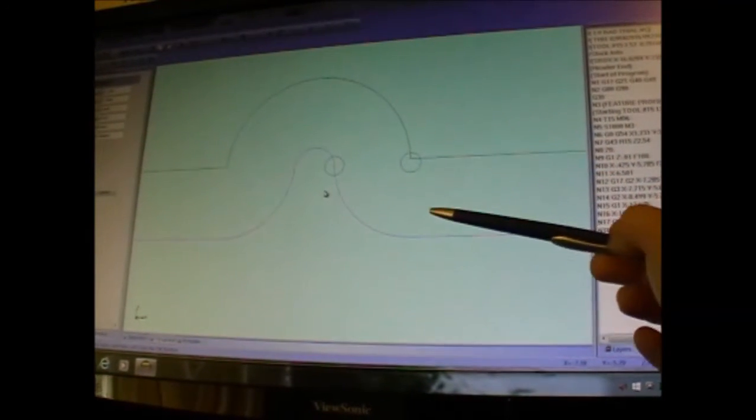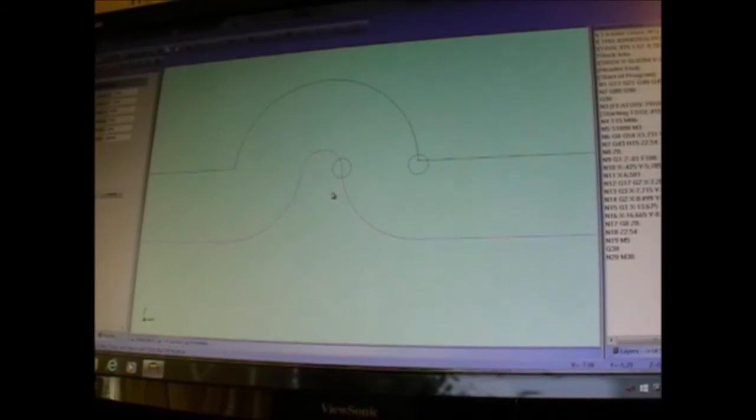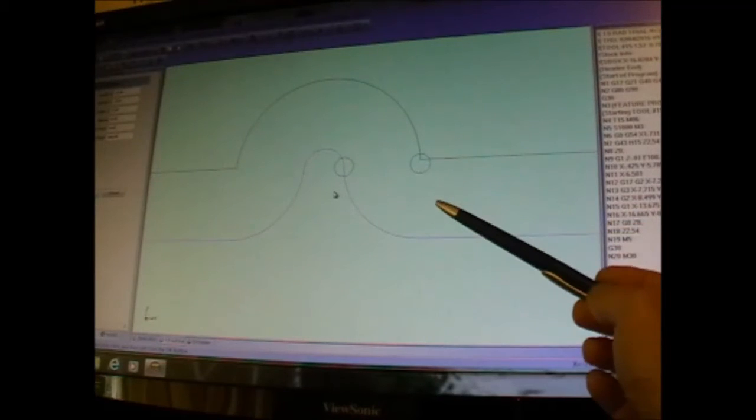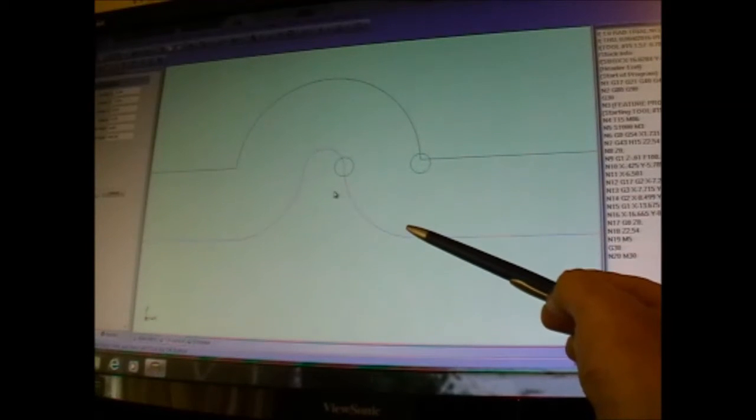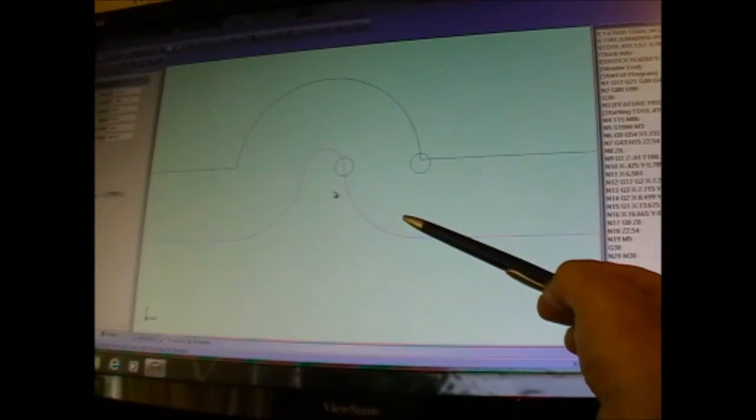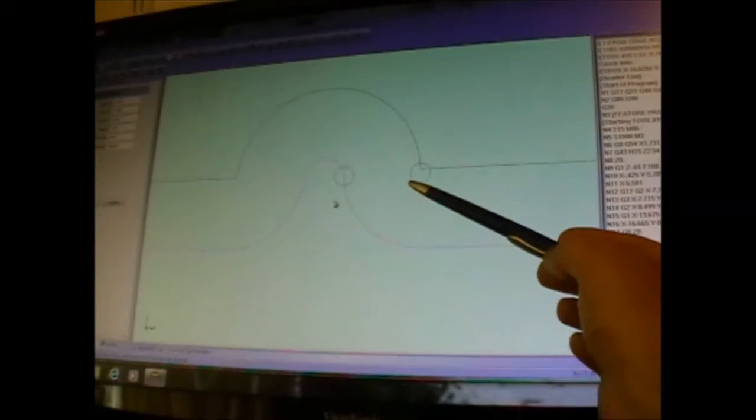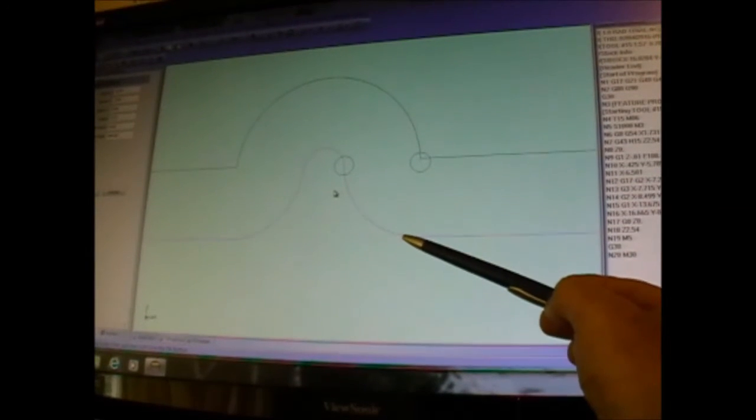And then the next two values are an I and a J, and what it is specifying is relative to the end point of the toolpath where this all started, and this is incremental IJ mode, so it's incremental relative to that point.